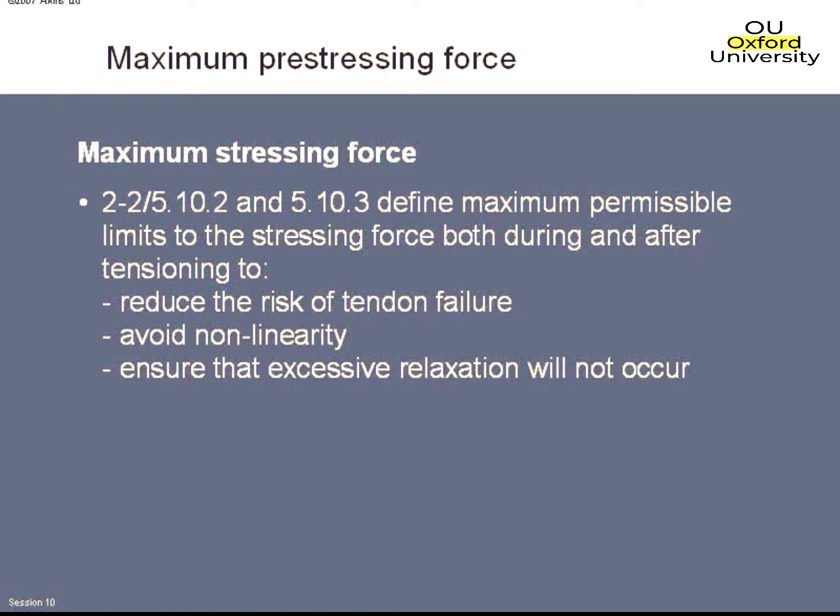Also, as we get towards the ultimate tensile strength, the strand doesn't behave linear elastically anymore, where we start to get some sort of plastic non-linear behavior. And again, we want to try and keep well away from the non-linear region of the stress-strain curve, because otherwise it makes it very difficult to check the pre-stressing force by using extensions. It's very difficult to do that if you haven't got linear behavior.